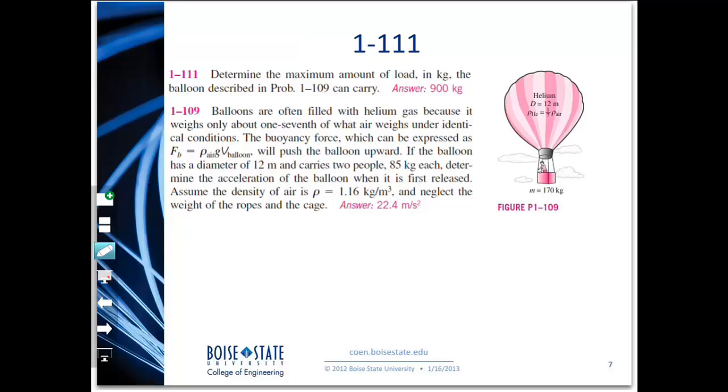So to solve this problem, what we have to determine is what is the maximum amount of load it can carry. Okay, so the forces acting would be the buoyancy force, which is taking the balloon upward, and the weight. And here, many people would make a mistake. The weight here would be the weight of the contribution of the people and also the weight associated with a certain mass of helium. So we have to compute that.